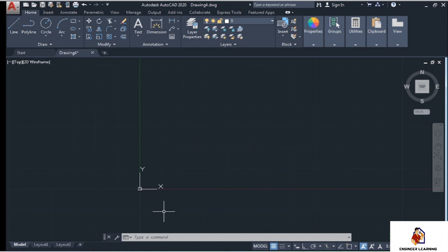Now let's understand how to use AutoCAD tools. We are always going to start a drawing with the help of draw tools. These are the core tools of AutoCAD which will help us to draw the basic shape of our plans. In AutoCAD, there are two ways in which we can activate a tool. Either you can click on the respective tool icon from the ribbon panel, or you can use its shortcut command. Click on the line tool to activate it like this. You can see the crosshair cursor has now changed to a plus sign, indicating that the tool is active. To come out of a tool, you will need to press the Escape key on the keyboard. Now the cursor has changed back to the crosshair cursor with a little box inside it. This box indicates that it's back to its normal selection mode.